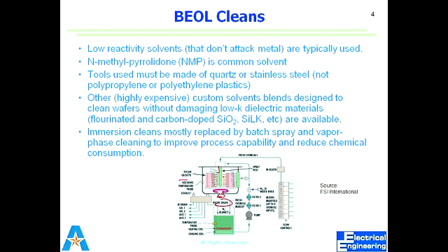After you deposit a metallic layer, then you cannot use the RCA process that we use in the case of a silicon wafer. Now we have the metallic layer, so we cannot use highly reactive acids, the Piranha clean or the NH4OH or even the HF cleanup process.